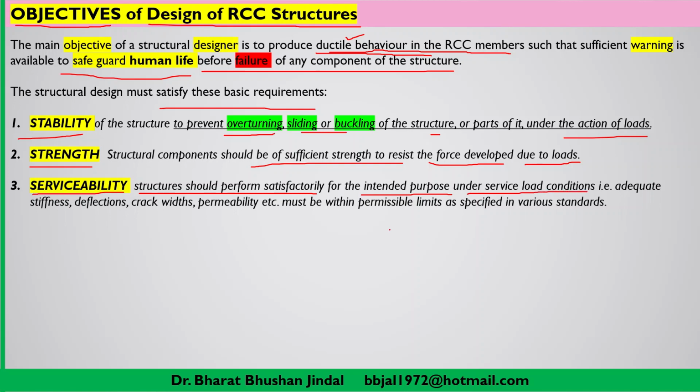That means it should have adequate stiffness. And if there is any type of deflection, crack width, permeability, etc., these must be within permissible limits, and these permissible limits are clearly mentioned in various Indian standard codes, such as IS 456.